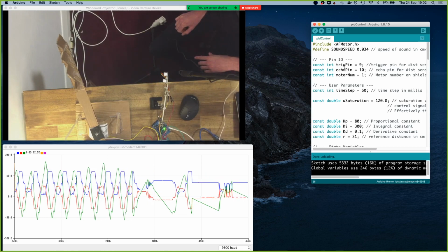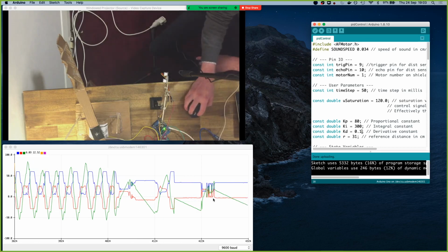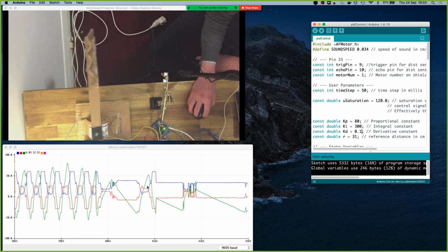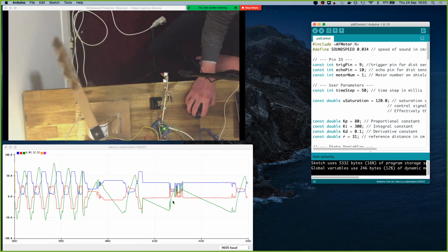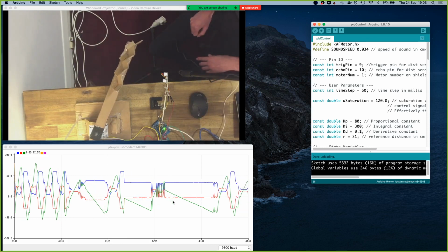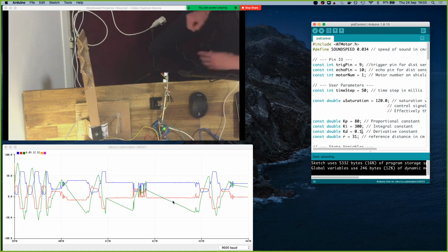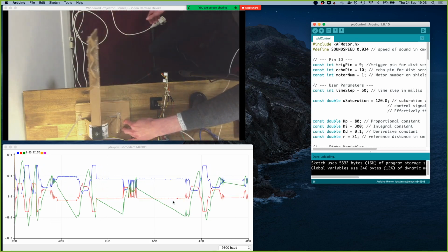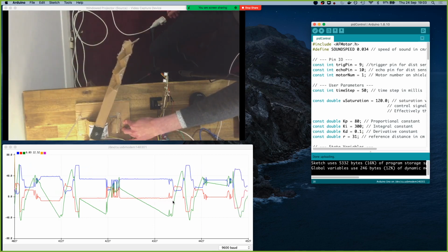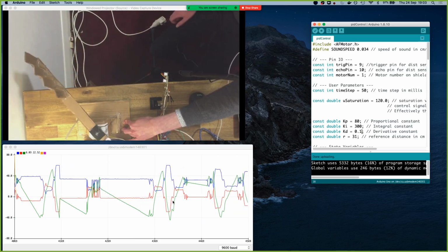So you're going to have more responsiveness of the control signal to changes, particularly in something like this. You see much more jumping around of that control signal compared to what's going on in the integral term. It's trying to do something. We might reach that equilibrium at some point. That's getting sort of close there. Let's give it some disturbance. It takes a while to come back, but it's not going too badly.